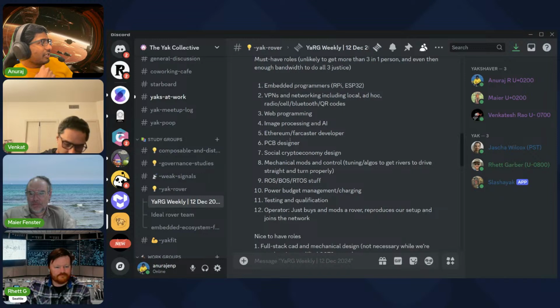So there is a voltage called VIH, V input high. It's generally around 3 or 3.3 something. So if the signal goes above that, even from a 5 volt range, then it will clock in as high.